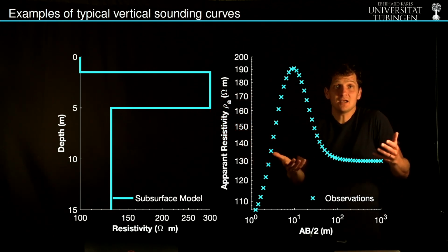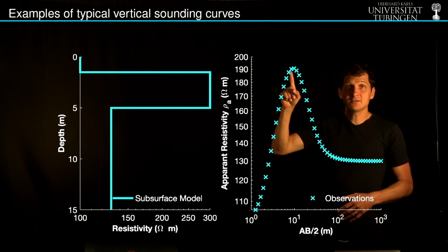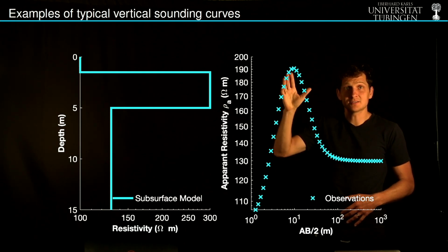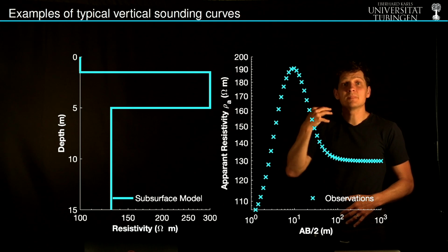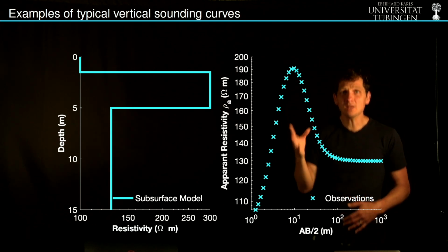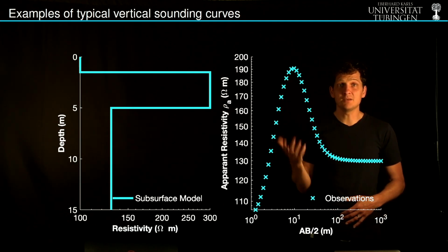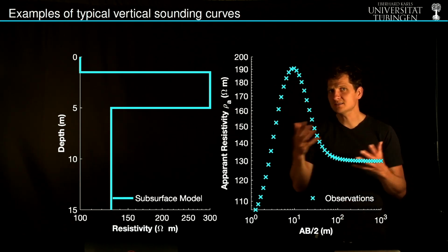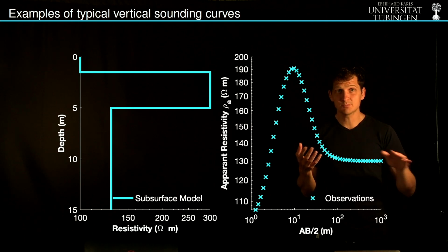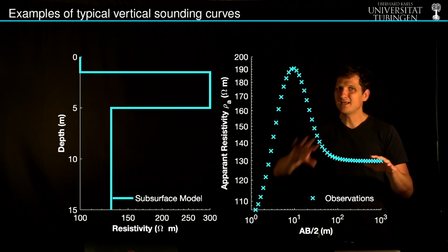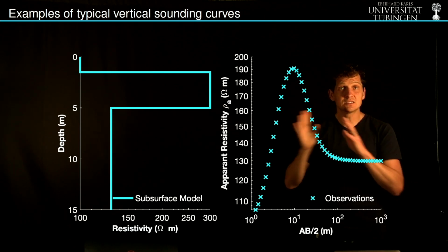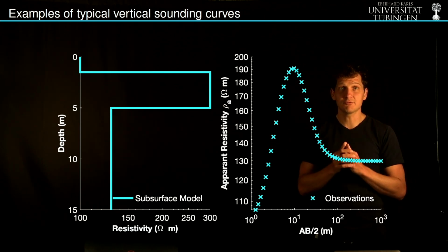And therefore, again, apparent resistivity is diagnostic, so there is a lower resistivity layer somehow sandwiched, but the magnitude of this resistivity cannot directly be inferred from the apparent resistivity. Okay? So memorize this. This is diagnostic. You can get some first order interpretations, especially at the tail ends, but everything that's in between is a bit of a gray area because the resistivity method does a lot of vertical averaging.